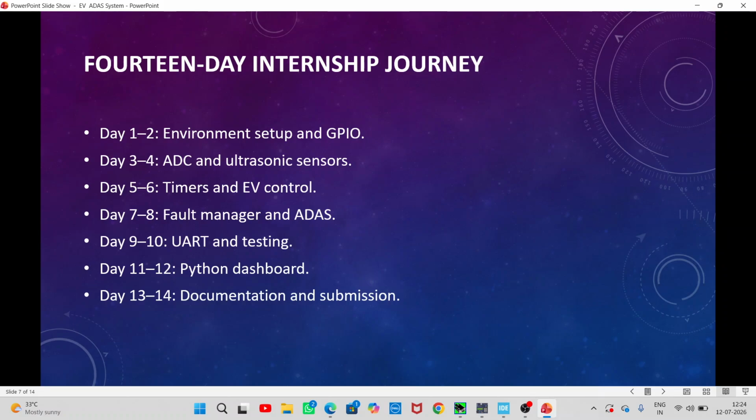We see how the ultrasonic sensors work and how they detect an obstacle. Generally an ultrasonic sensor measures about 2 to 400 centimeters. We fix one threshold value. If the calculated distance is above the threshold value, no obstacle is detected. If the calculated distance is less than the threshold value, then it detects that an obstacle is there. This is the work of the ultrasonic sensors. Here we use 3 ultrasonic sensors, one for front detection and others for right and left detection.